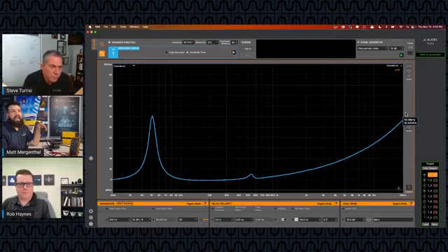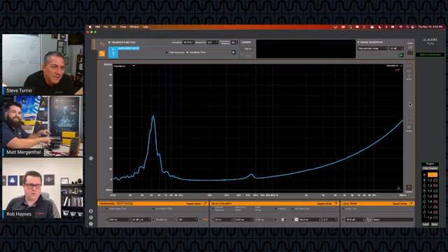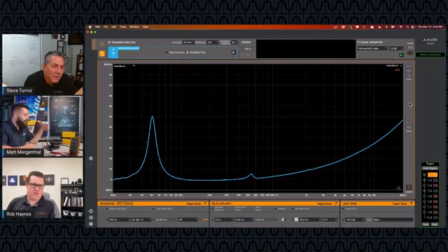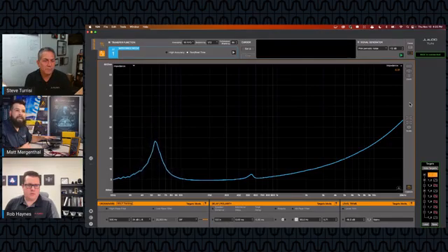Sweet. And what's neat is this is real time. Like it's actually in real time. I guess clapping doesn't make a big deal out of it, but if I touch it, you can see that it's live. So this is exactly what I was referencing when I mean you can put a door panel or a grill on top of a speaker, and the second it makes contact with that speaker, you're going to see a change in that impedance measurement.